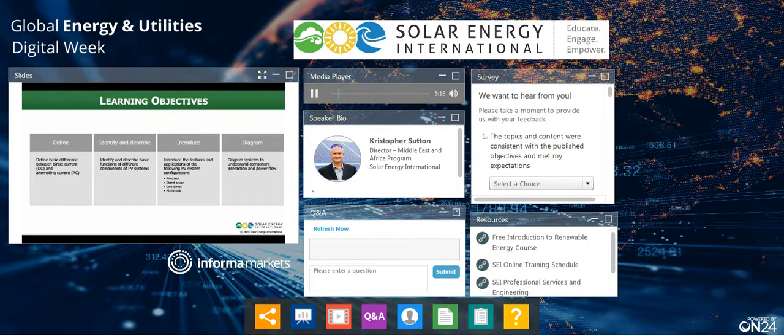Standalone, meaning something that's off grid, that's not utility connected, that is an independent power system. Grid direct, when we say that, we mean something that's going to synchronize with a local utility grid and backfeed power or connect to the grid whenever the grid's available. And then a multi-mode system is a system that can work as a standalone system or a grid synchronizing system with a lot of versatility. We'll get into some of that.